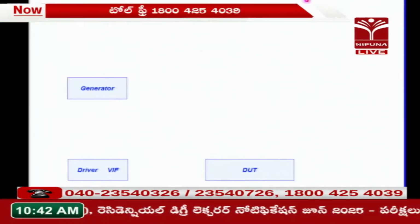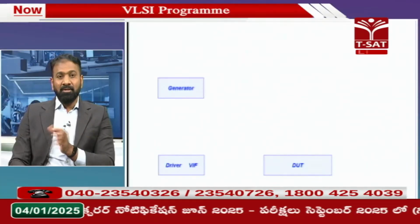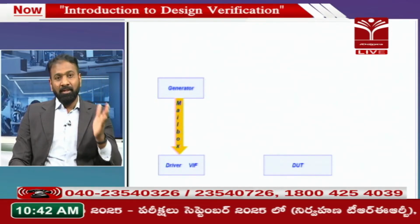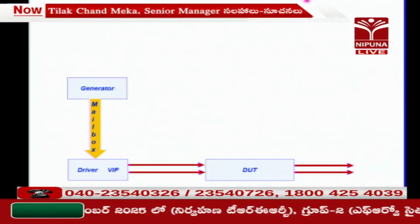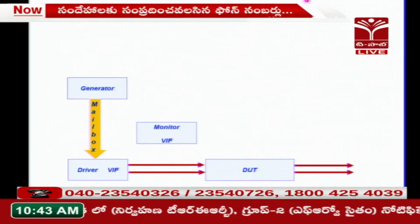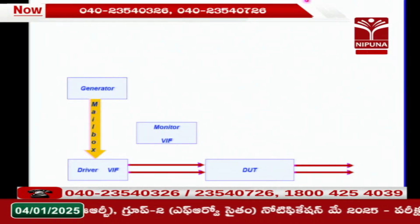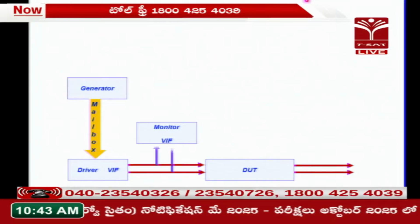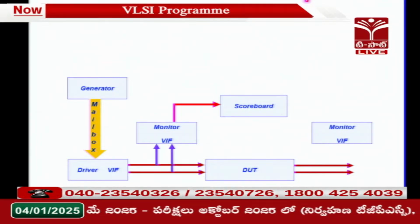What will the driver do? Driver will get the transactions from the generator and send it to the design. So generator is going to send the data to the driver, and the driver will pass it on to the signal level of your DUT. Now on the design side, like I said, you have to monitor your transactions, the signal values which are getting into the design and the output of the design. So the inputs and the outputs have to be monitored for the design, and then you do the scoreboard checking.